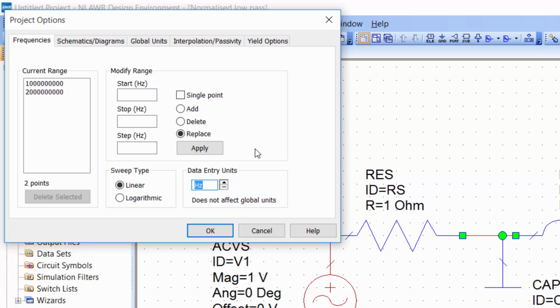This is equivalent to 0.16 hertz. And hence we must make sure that we get the right frequency range to capture that. So I think that a good frequency range to use would be something like 0.001 hertz. So we're going 2 decades below our corner frequency, and then we can have 10 hertz as our final frequency.